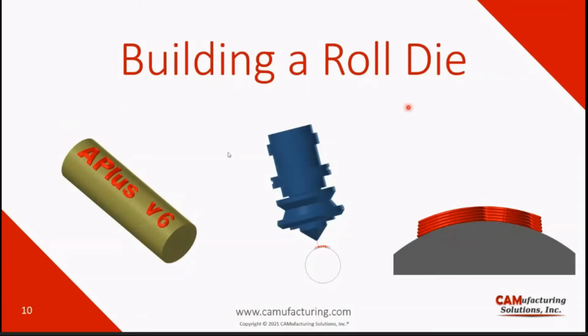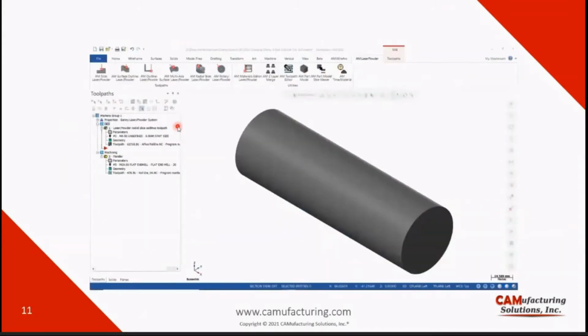But by using DED and some surface finish at the end, you can have it way cheaper and way faster. So in order to do that, we have a tool pass called AM radial slice. What it does is slice your model like the normal slicer, but on a radial basis instead of a planar Cartesian system. So let's see this example.